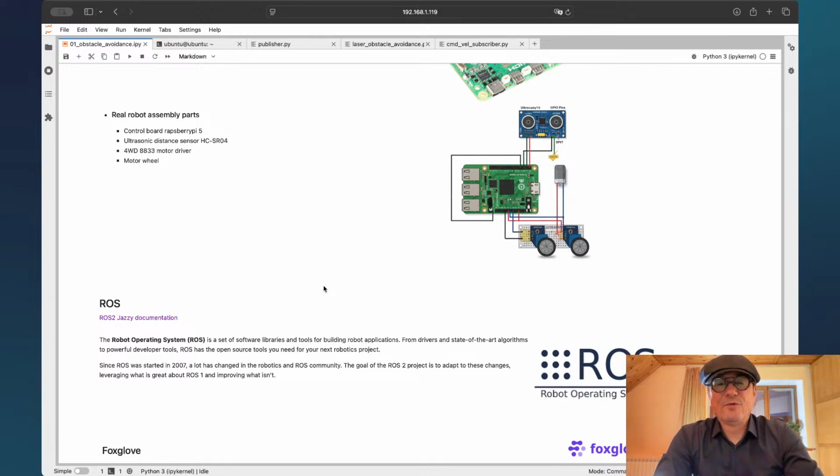Also for understanding the environment, like stairs and obstacles, we need different kinds of sensors. For example, to check changes in height, such as stairs or other obstacles, we can install a set of sensors on the robot's body.